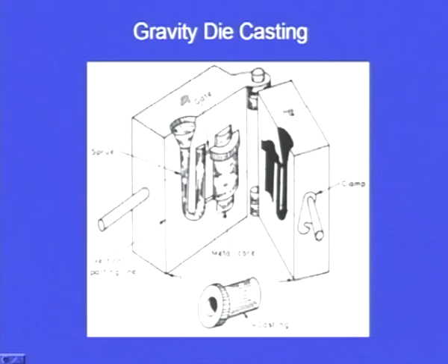And there should be a provision to pour the molten metal, which we call the sprue. Sprue is the passage through which we pour the molten metal into the cavity. So, this is the sprue. Even the sprue is engraved. Half of the sprue passage is engraved in this box, and half of the sprue is engraved in this.